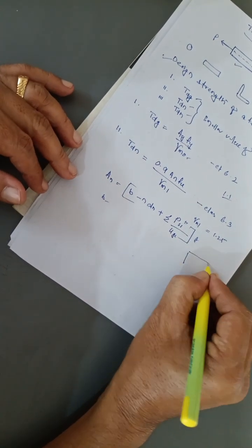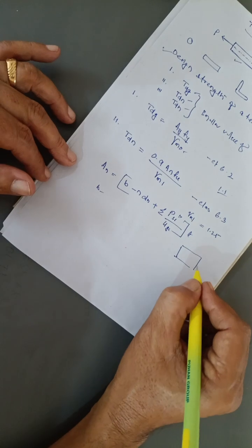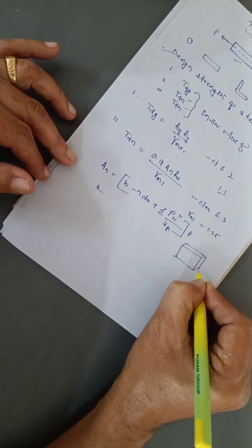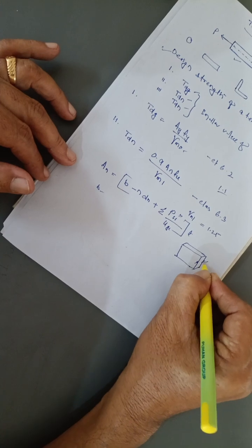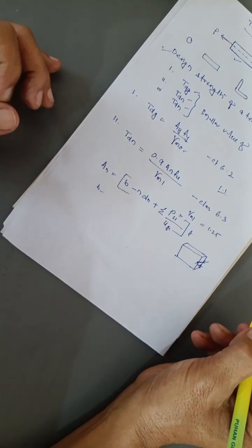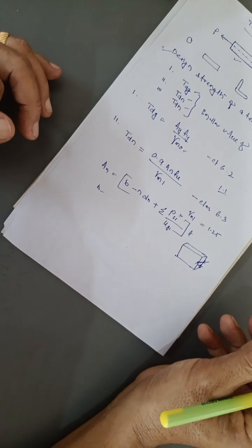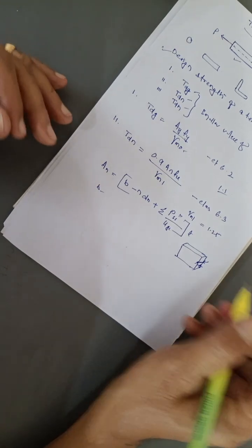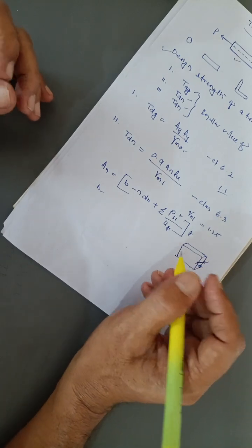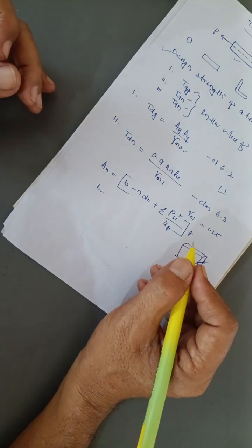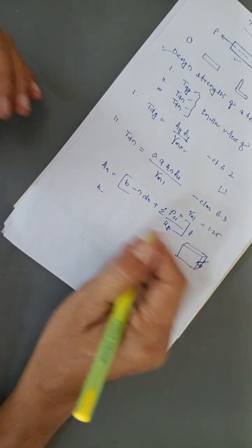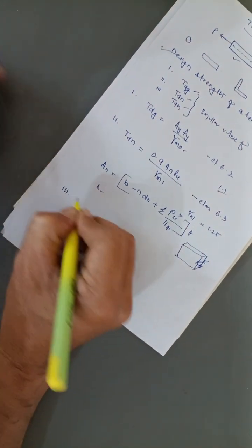Let me consider this as the plate and draw the thickness here, which we consider as t, generally the thinner plate thickness. n is the number of bolt holes in the critical section, and i is the subscript for the summation.